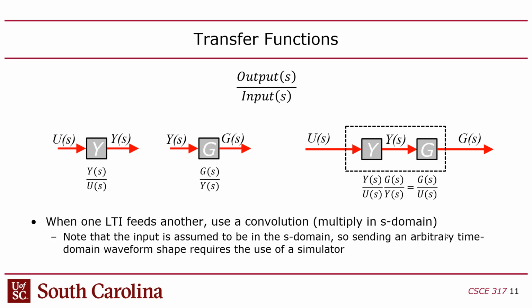So you can do that. And then once you do that, you want to conceptualize the combination of the plant and the controller as a new transfer function, right? I want to compose them. So how do you do that? It turns out with transfer functions, it's very simple. You just literally multiply them together, right?